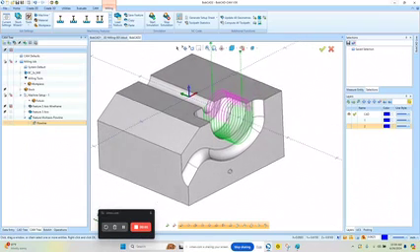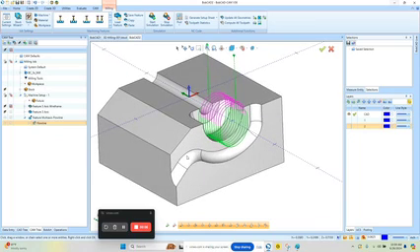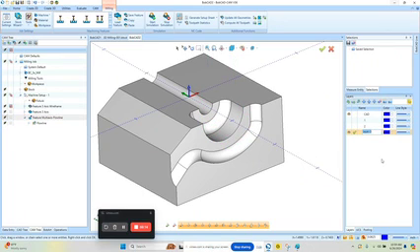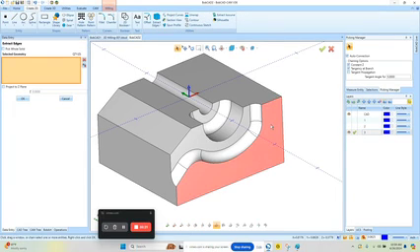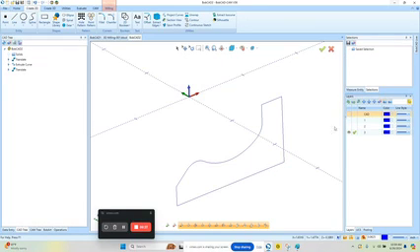Alright, now that we've gone through a flow example, let's look at how we can drive some toolpath along this curve here. So we're going to just blank this out. We'll create a new layer, make it active. From here we're going to do 2D, extract edges. We're going to pick this face and choose OK. So that gives us the geometry we want to drive with.